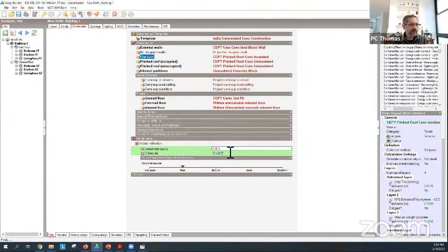Now, if you had some idea of what the leakage rate was because you do a blower door test, if you look up, say, Passive House, which is a rating scheme I'm sure you've seen, they do a blower door test in what's called an N50, okay?